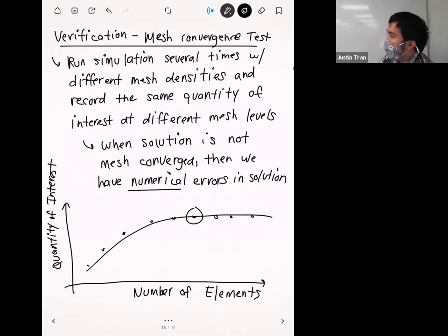That's the kind of mesh density that people are probably working with in industry. And that's why they force you to buy the software, right? If you could perform real engineering work with the free version of ANSYS, then ANSYS, the company, is probably doing something wrong. So the point is, don't be discouraged if you don't get mesh convergence on your final projects. I would be very surprised if you could, honestly. But it's still important to do.